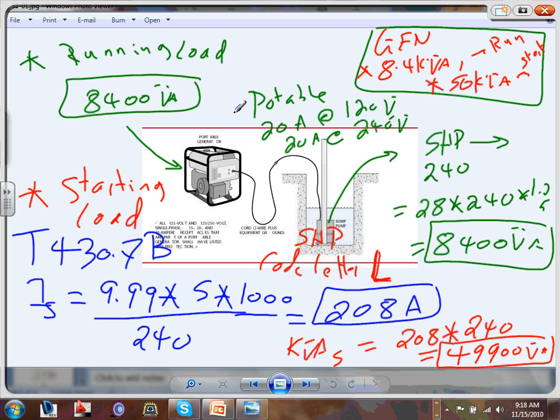Instead of slamming a 4,000 amp load from the utility down into the generator and bringing the generator down to a halt and stopping completely, you take the 4,000 amp load and chunk it into chunks of loads. So they say, okay, instead of slamming the whole 4,000 amp load, we're going to take the first 500 amp and transfer them. Now, the only inrush that the generator has to be able to handle is just for the first 500 amp. Transfer it within 10 seconds, up to speed, running. Now it goes all the way up, it goes down within 10 seconds, now we're stable. Go to step 2.